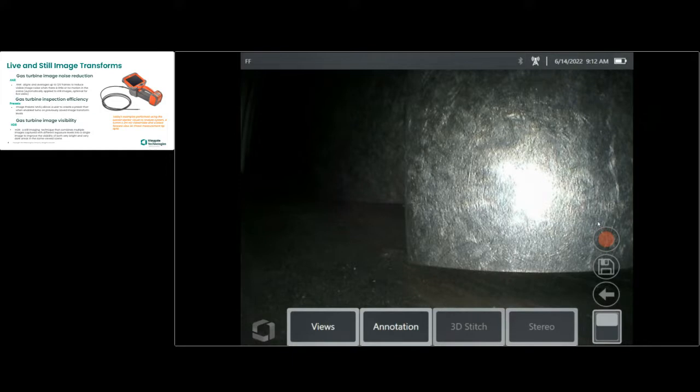And you can see here, I have a frozen image of a compressor blade. You can see how that compressor blade's got a hot spot in it. Let's say that that's the area of interest that I'm interested in. You can, again, see on the Mentor Visual IQ on the bottom, we have our dynamic soft keys. These are cool because they change no matter what you're doing with the system, whether you're doing file management or measurement or analytics or live or still, they'll change and provide you the tiles for what you most likely will want to use. And just to share, you'll see this little button on the bottom. You can go back. There's 8 of them there. So you can go back and forth and see everything that's in there. In this case, we're talking about probability of detection.